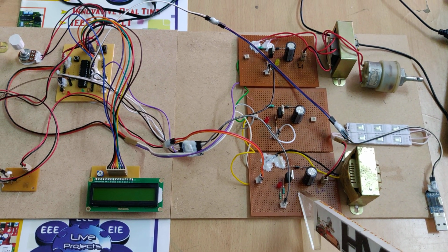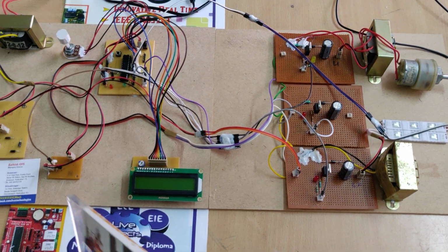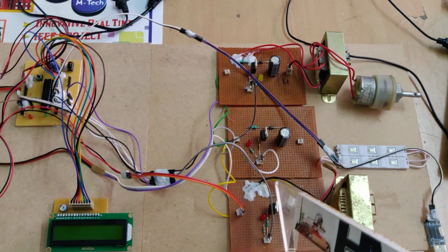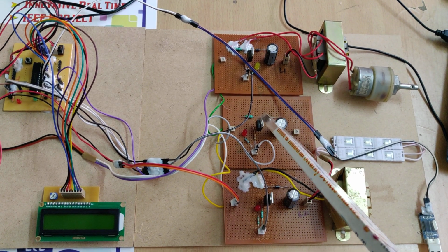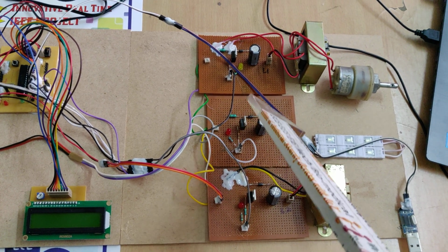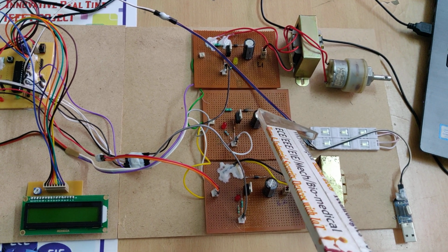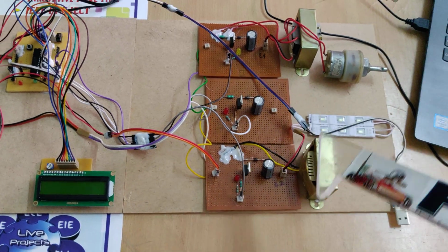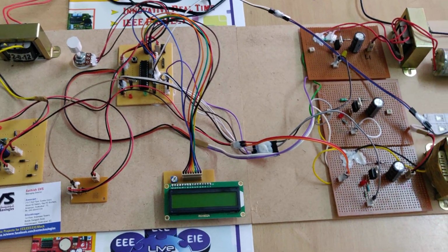And coming to the operation, whenever we switch on this kit, it will check the main input voltage and the reference input voltage. We are going to control that by changing the pulse width modulation to these MOSFETs, nothing but the on and off duty cycle time. When it is on, the inductor will charge, and when it is off, the same energy is discharged to this capacitor, and the capacitor will charge. Based on the on time, the output voltage increases or decreases, so it will be monitored continuously on our laptop screen also. So let us see the demonstration.